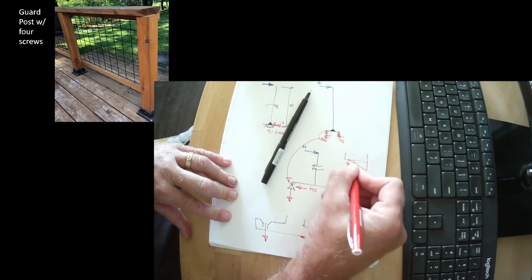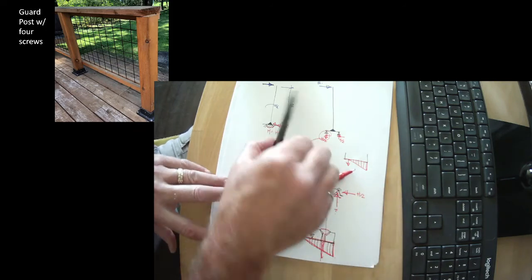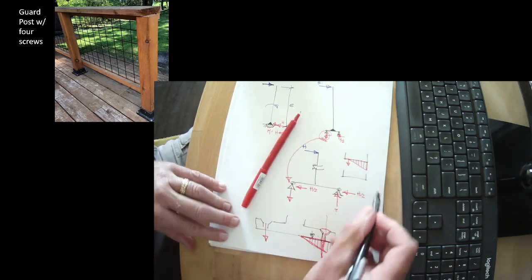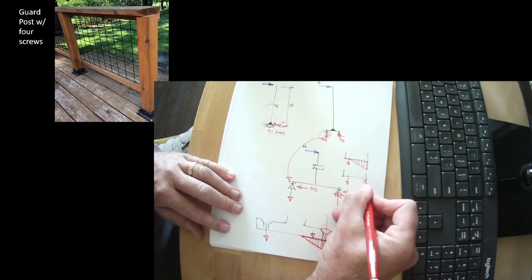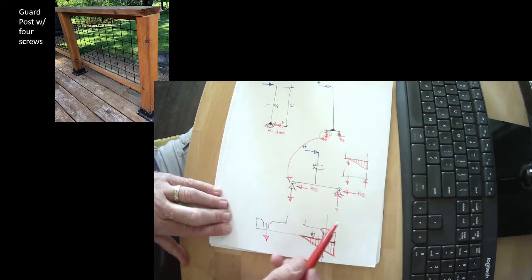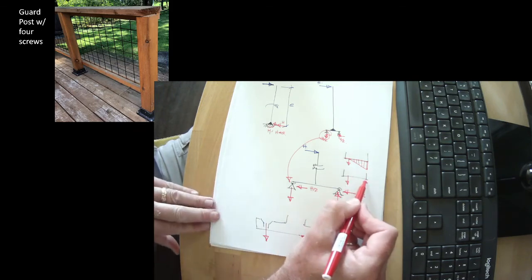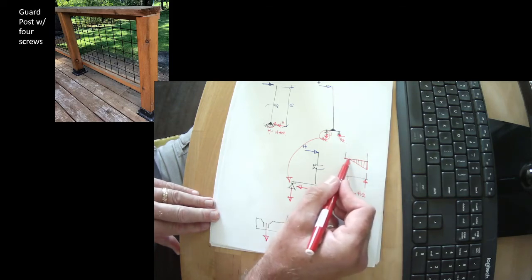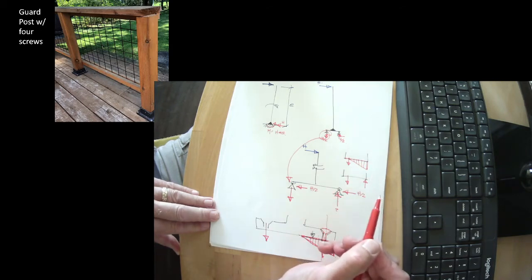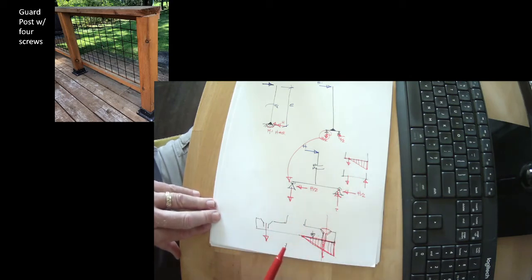reality might be this at one end of the spectrum. And it might be this at the other end of the spectrum. So the center of reaction for that bearing might be right at the very tip of the plastic, or it might be distributed through the whole compression zone from the middle of the screw to the compression side. And we don't know where it actually is. That would be an extraordinarily complex problem. So to put it at the middle of the screw is a reasonable thing.